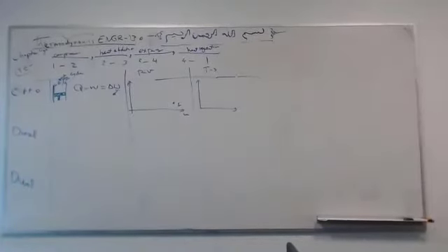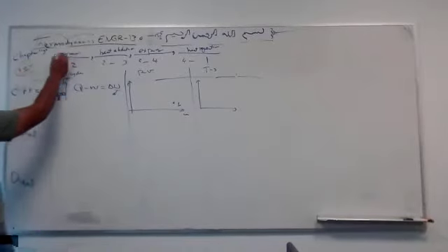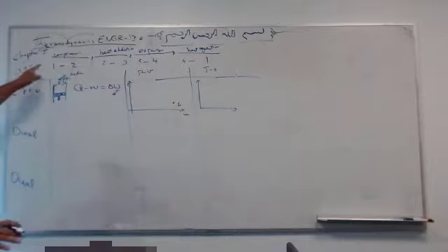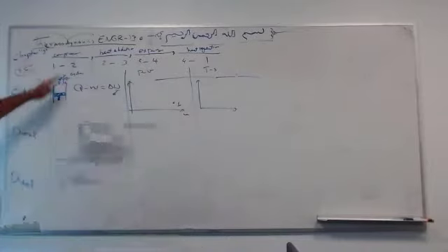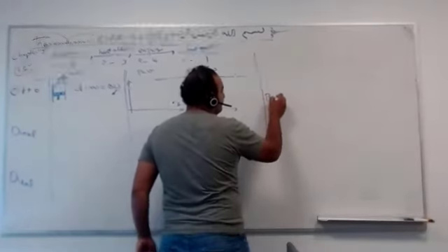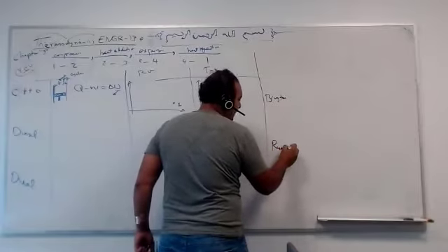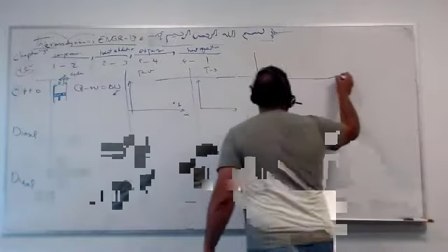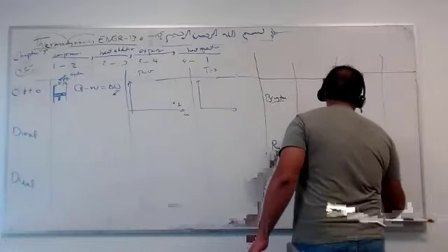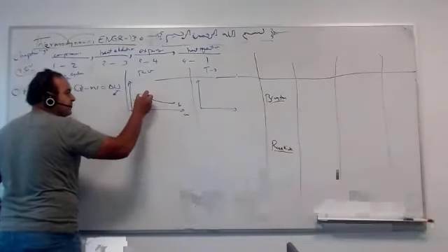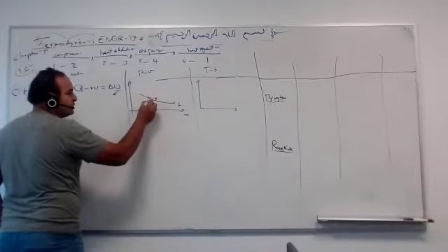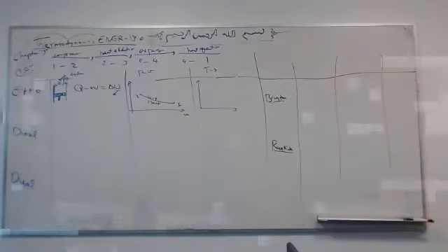So here we have the PV diagram. We have compression, reversible, adiabatic, so isentropic. For all these cases, including the Brayton and Rankine, we have isentropic compression and expansion. So here we have 1 to 2, compression, which is isentropic. Here, in the Otto cycle, we assume the heat addition at constant what?